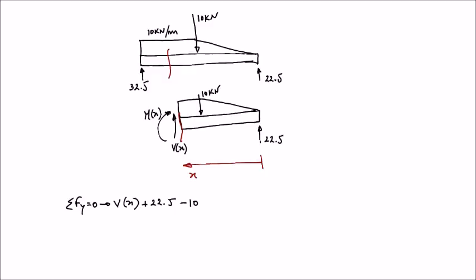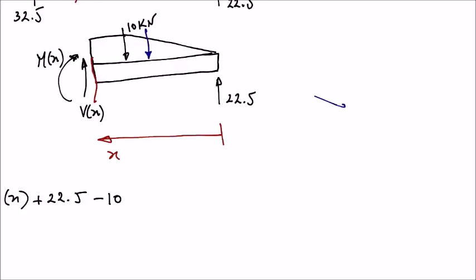The only thing we need to consider now are the distributed loads. For the triangular distributed load, we need to replace this triangular distributed load with an equivalent force located at the centroid of the triangle. This equivalent force